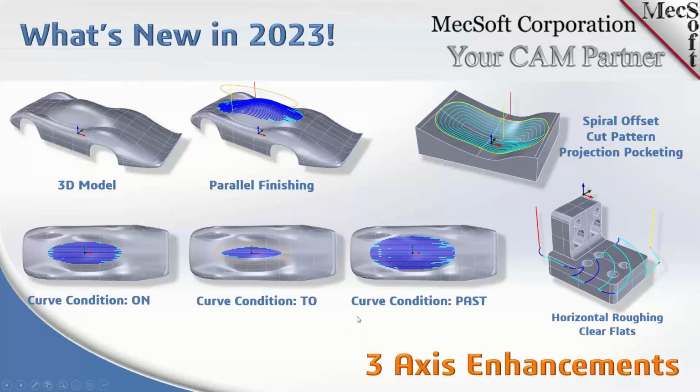Now here, I spoke about the curve conditions on, to, and past. Now you can do these on a curve, any curve. So if you look at the top left corner here, this is a sub D model. And really the only thing that you can select here is the actual sub D ISO lines you see here. And if you want to do some remachining in a certain area, you may not want to be limited to these ISO lines.